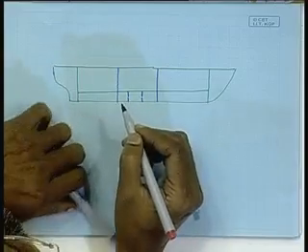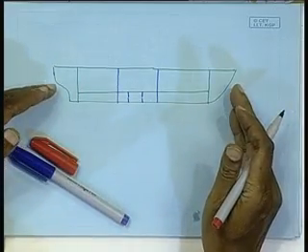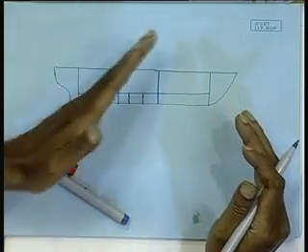By one continuous plate, what do I mean? The ship length could be 200 meters. So, we do not produce 200 meter long plates. It will be only 10 meters. So, 20 of them will be put one after another, and they are welded. Not at one go, but in blocks, in units, that is a different issue. The whole point is they are continuous, meaning nobody is penetrating them.